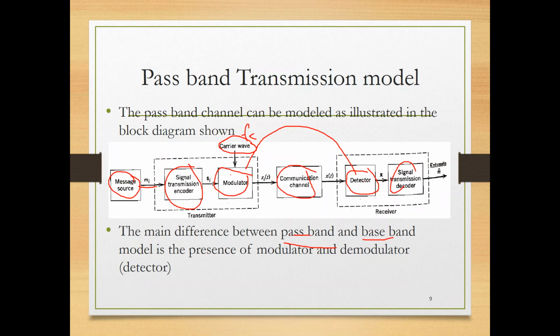So this can travel through the air, wirelessly, but baseband cannot. This is for wire, this is for wireless. This is after multiplying with a carrier, this is before. So before the modulator, you have baseband, and after it, you have passband. Good, clear?